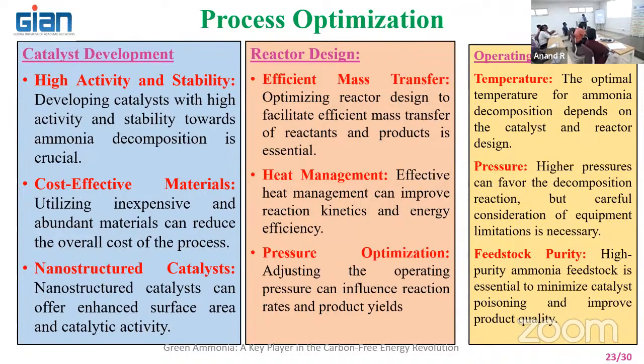Whereas if you talk about, let's say, plasma, plasma is also similar to microwave. We talk about electrical heating or the thermal mode of heating. It is coming from the surroundings. As we know, heat goes from high temperature to low temperature. So the temperature is around 1000 to 2000 degrees centigrade, and ambient temperature is maybe 30 degrees. Instead of reaching the desired temperature in the reactor, due to the atmospheric temperature, heat loss is going to happen.